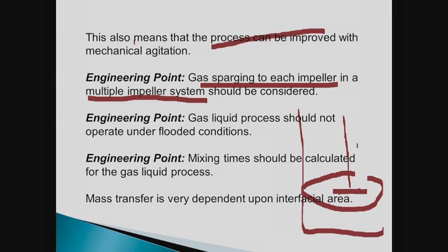That's your major reactor right there. The rest of the tank was a bubble column. So if you had another impeller here and sparged to both impellers, what you've done is doubled the, well, not exactly doubled, but probably you'd get 40 or 50% increase in production, maybe 60.